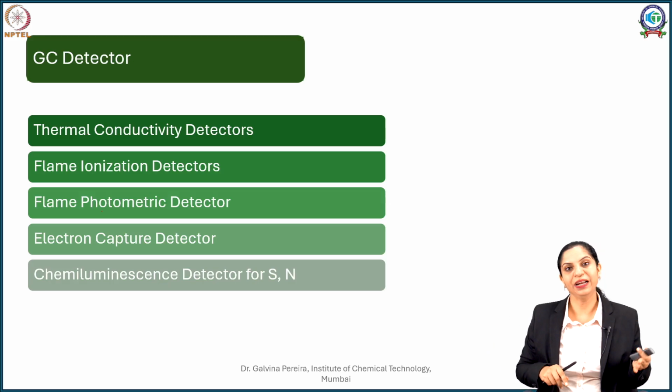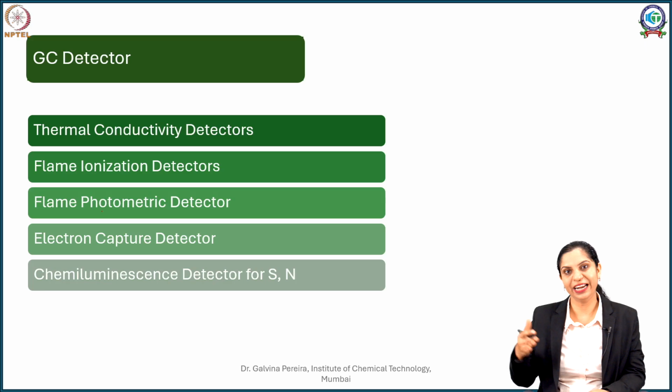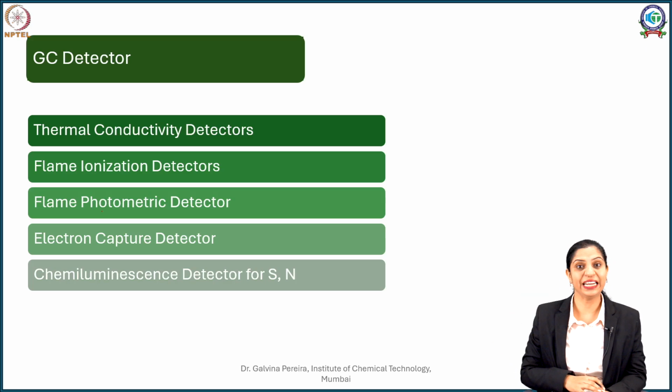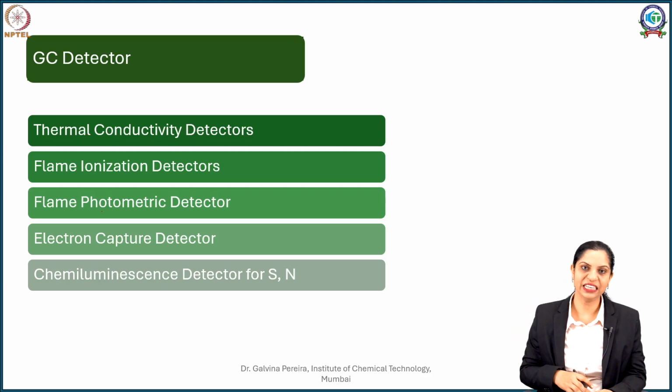In the same way, with normal helium, you check how much that gas can ionize, say for example, your mobile phase. Now compare it with your analyte moving through that column. The degree of ionization changes when you have a compound coming out. How much is that change? That is detected as a peak. In the same way you can see the intensity. Certain times, certain metals produce light of a different intensity. So that is where you measure your light intensity. In a similar manner, you can see the flame color change in intensity and analyze it, and that is what is called flame photometric determination.